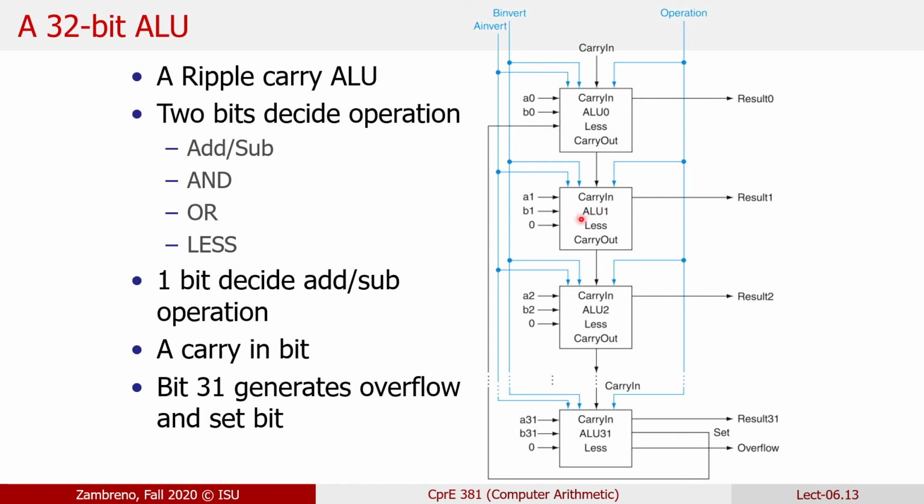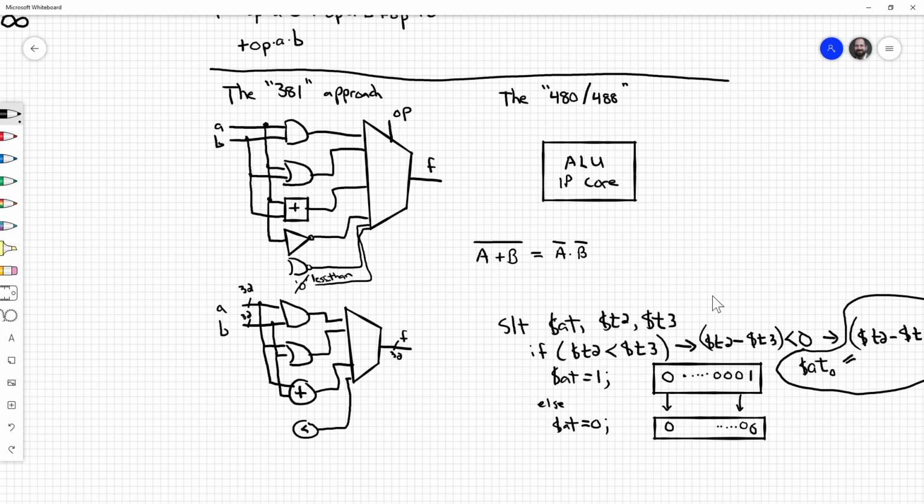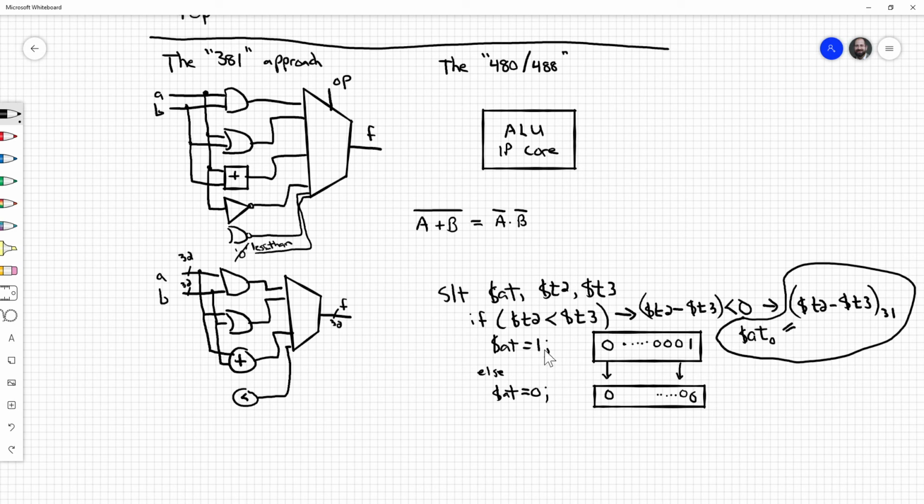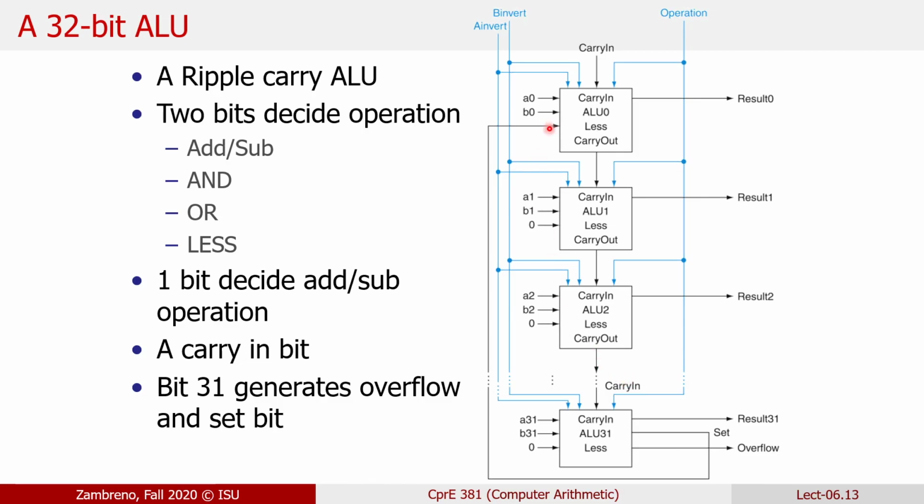Which for all these other bits, if it's a less than operation, the result is always 0. Again, don't overthink that. Look back to this slide when you're designing this, that no matter what, the result of the less than operation is either binary 1 or just binary 0. So all those other bits are always going to be 0 no matter what. So we can actually hard code that in our design. For all these other bits, if it's a set less than operator, we know what the result is, it's a 0. It's only for that least significant bit that is either potentially a 1 or a 0, depending on what the result of the subtraction operation was. And that's what we're grabbing from that most significant bit.